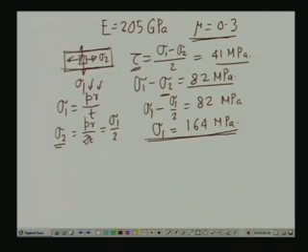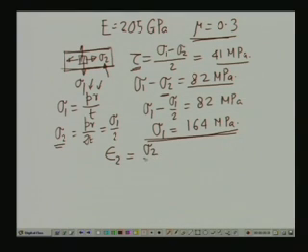which is 82 MPa. Now, if we know the stress, then we can find the strain. We have a strain gauge which is fixed in the longitudinal direction of the vessel. On the cylindrical vessel we have fixed one strain gauge in the longitudinal direction, which will record the strain in the normal longitudinal direction. So, we will have to compute the value of the strain in terms of the stresses. The strain in the longitudinal direction, which we are calling epsilon 2 in line with the stress sigma 2, is epsilon 2 equals sigma 2 by E minus mu sigma 1 by E.